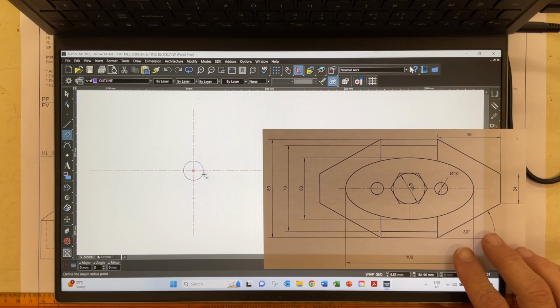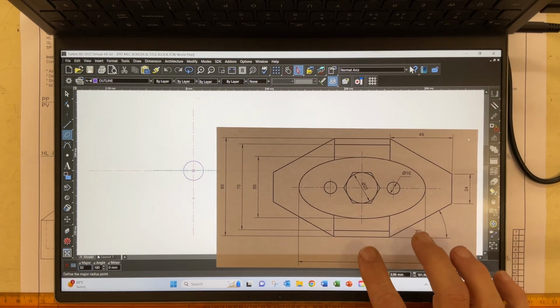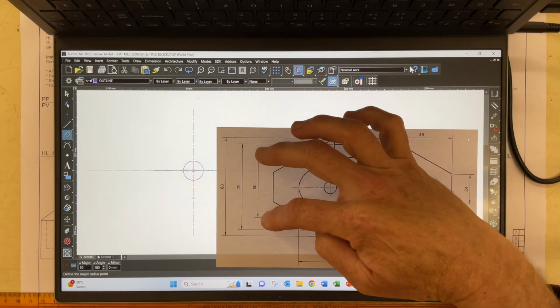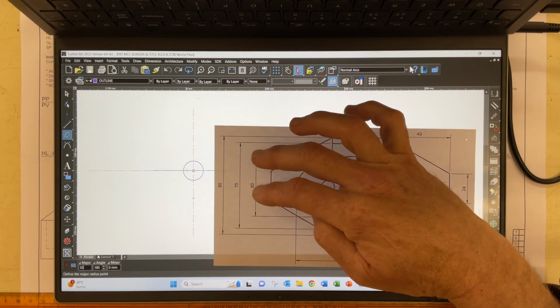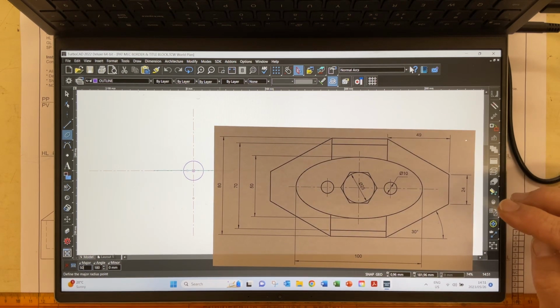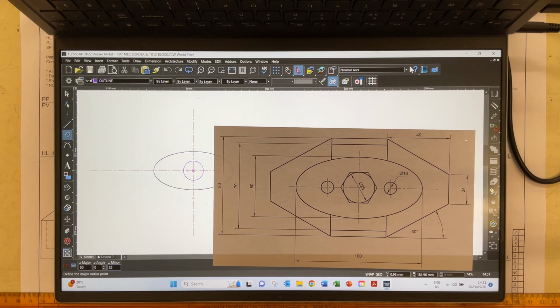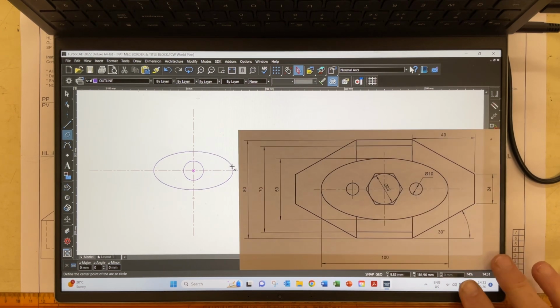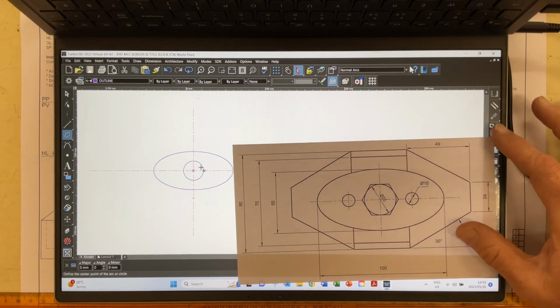Click in the center over there. Okay, major axis we said was tab 50. Okay, that's half of the 100. What is the minor axis? The minor axis is going to be 50. Half of that would be 25. So I go tab. That's the naught. Okay, press naught. Tab, and 25 would be half of that 50. Press enter, and there you go, you've got your ellipse drawn in beautifully.